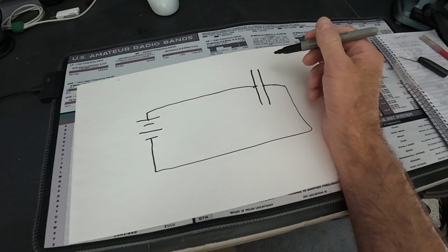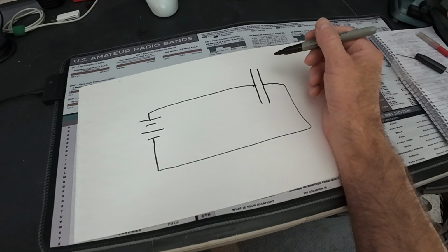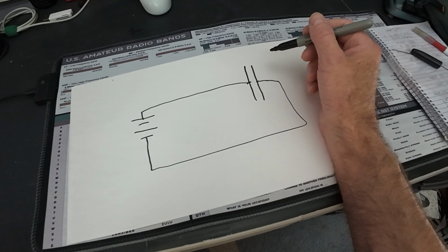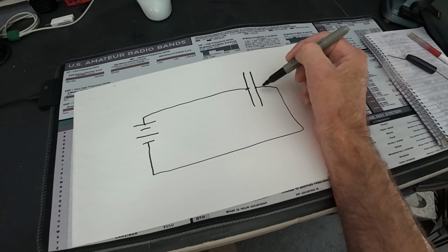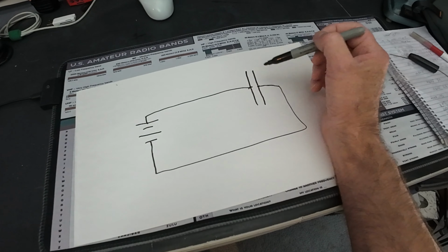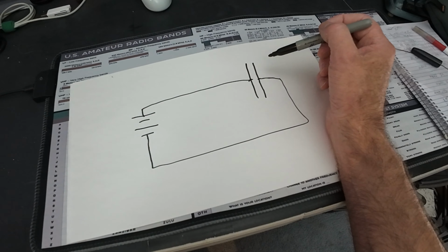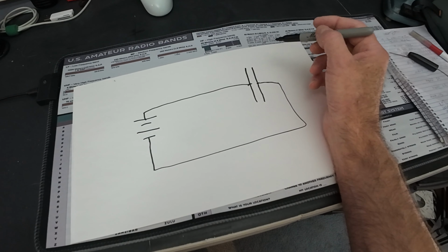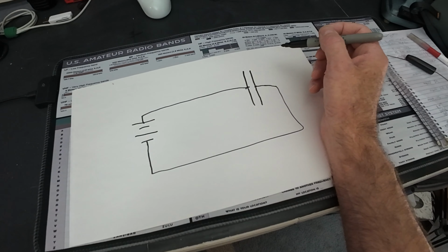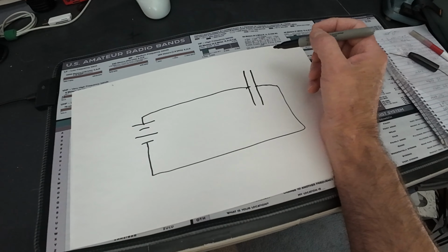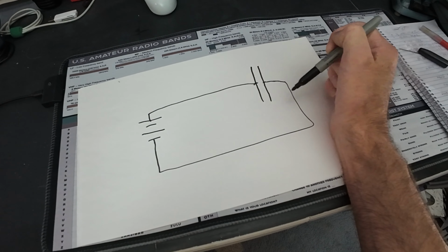If that happens, we didn't choose a capacitor with a high enough voltage range, because that should never happen. So therefore, there's no continuous DC current through a capacitor. It's impossible. And capacitors are rated in farads, and their rating determines basically how much potential it can store.